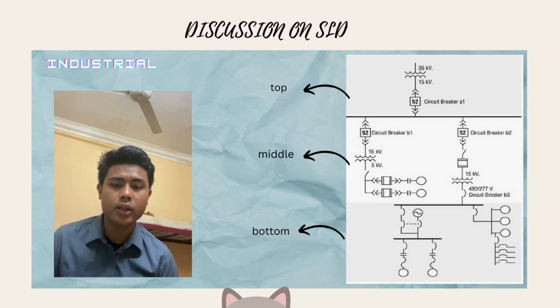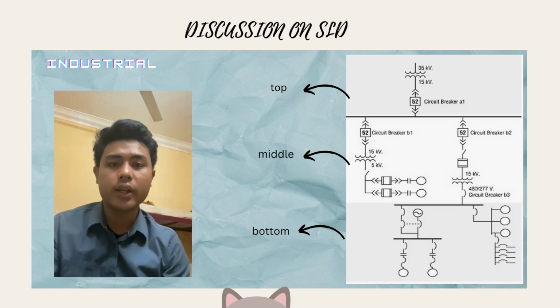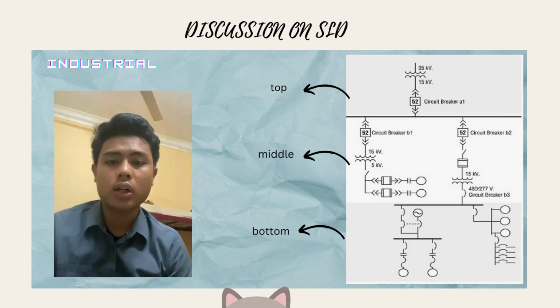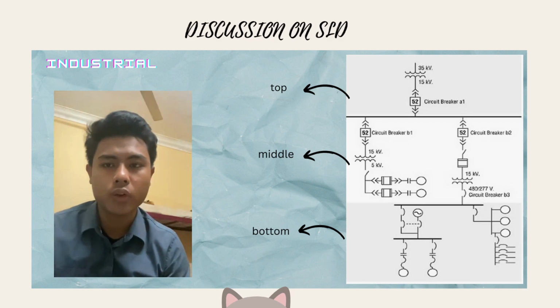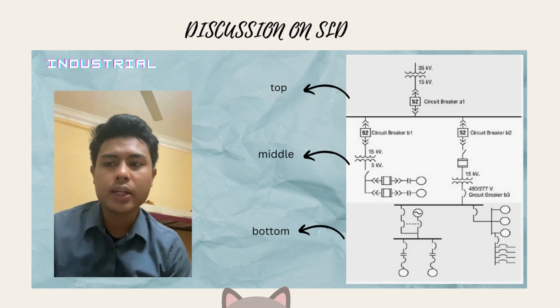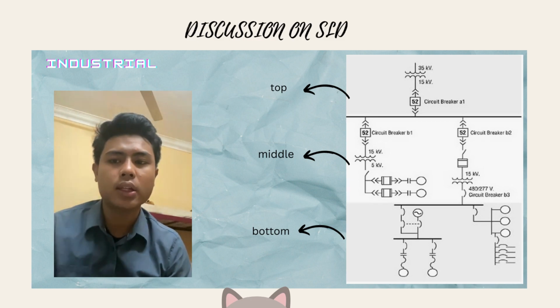Then the circuit breaker is encountered after the voltage has been stepped down. This is to make the load manageable. After that, a transformer is used to step down the voltage from 15 kV to 5 kV. A disconnect switch is displayed on the transformer at 5 kV. The equipment isolated under the transformer connects using the disconnect switch and goes to the two medium voltage motor starters.